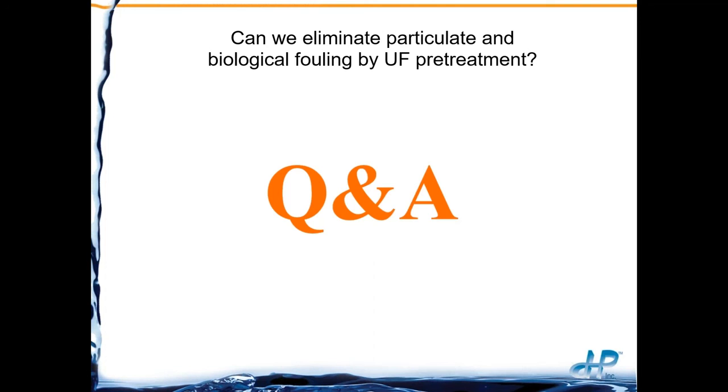The bad news: there's one contaminant that will pass right through an ultrafilter. It's a dissolved contaminant that will cause issues in the RO system, and that is basically the organics. Dissolved organics will pass through an ultrafilter and feed the bacteria that are in the piping and the RO elements and RO system itself when they built it.